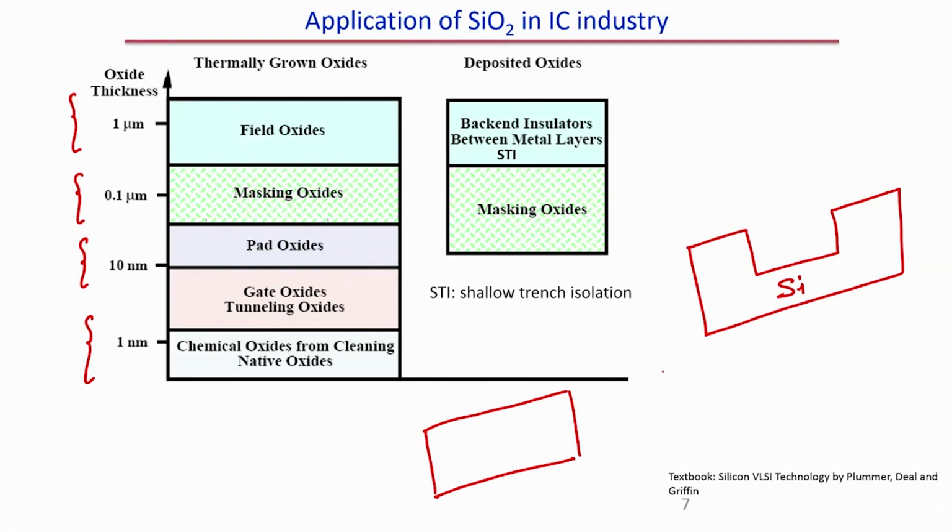See, I know what silicon etchants are, that can etch silicon, right. These etchants are KOH, potassium hydroxide, and TMAH, tetramethyl ammonium hydroxide, and these etchants are used for different applications. The application is the same, which is silicon etching, but they are used at different temperatures.